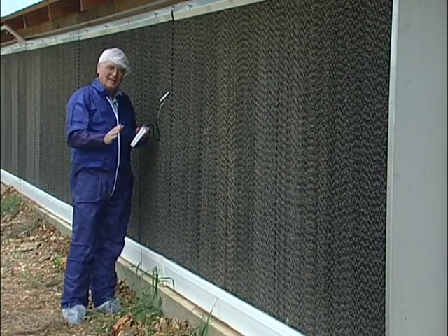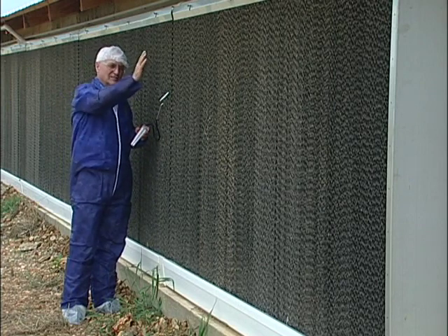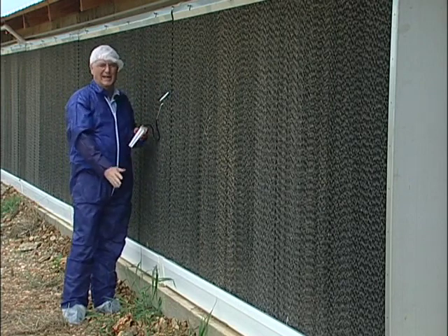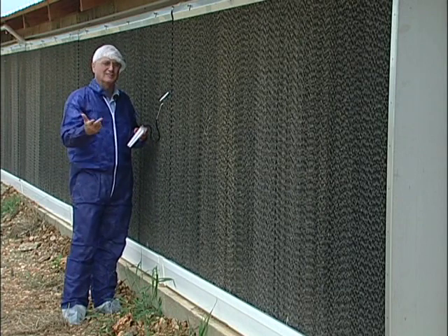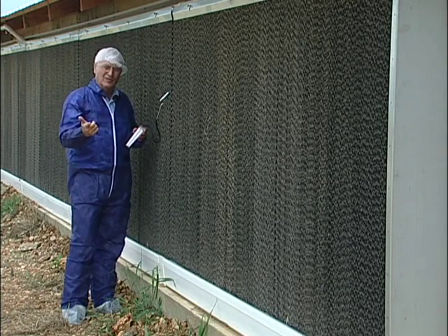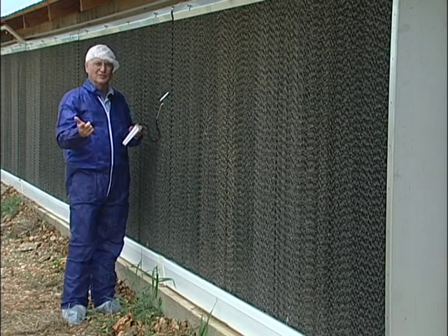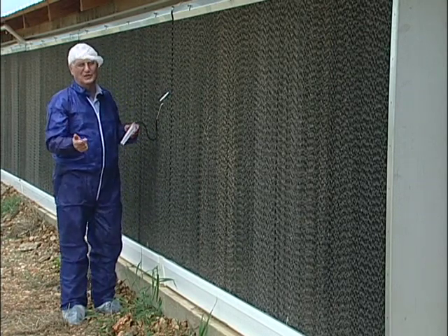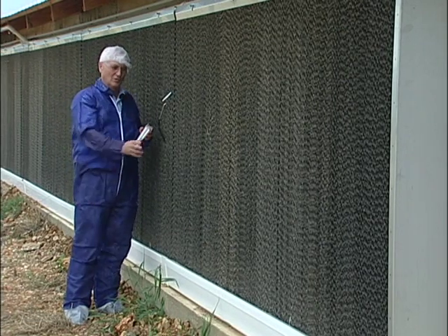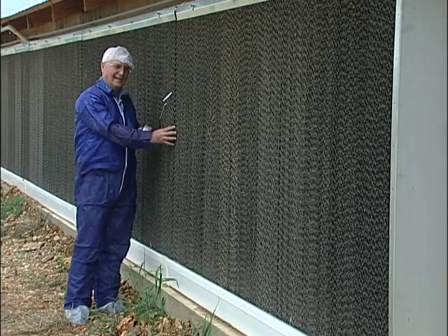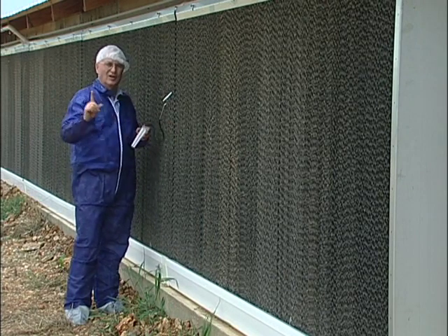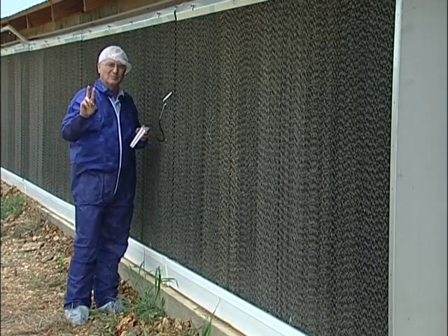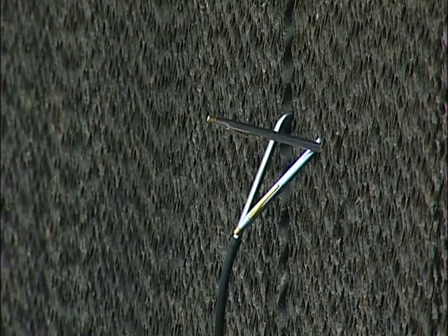Now, if you ever drive up on the farm and you can see water running down the face of the pad, then the system shouldn't be running to begin with. The humidity's either too high or your temperature's too cool, so your evaporation rate is not nearly what it should be. So the key to cooling the house without increasing the humidity is the way these pads are, number 1, sized, number 2, managed, and number 3, installed.